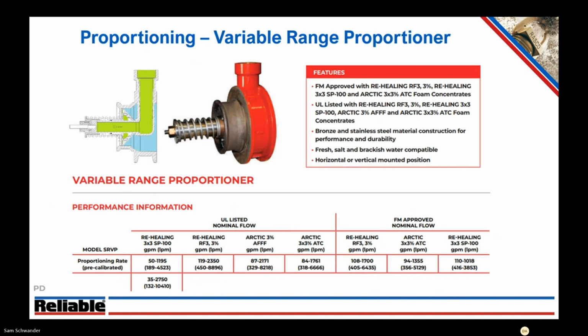And you might say, well, that's awesome. Why don't we just use this device for everything? You can see a cross section of the device here and how this really works. There's a wafer in the water path, and as the flow increases, it's going to push that more and more open. And the center tube has a cut in it, and it's going to expose that, allowing more and more foam into the riser system.